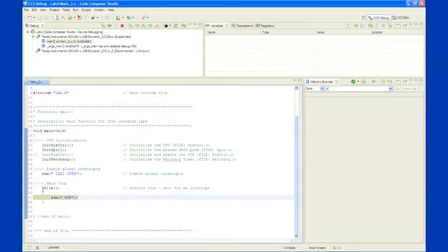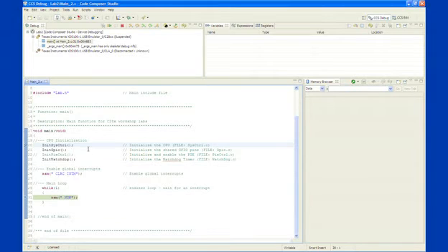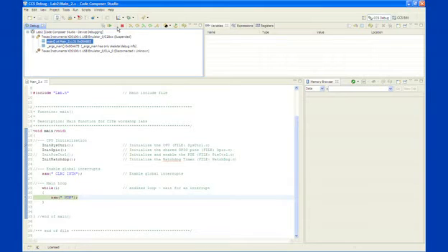So now we're in the main loop. Next I'm going to go to the top part right here and double click, and that sets a breakpoint. We want to test the watchdog out knowing that it's disabled. Alright, I'm going to run the code for a few seconds and stop the code. So we run and we stop, and you notice it's in the main loop. Once again, run, stop, in the main loop.